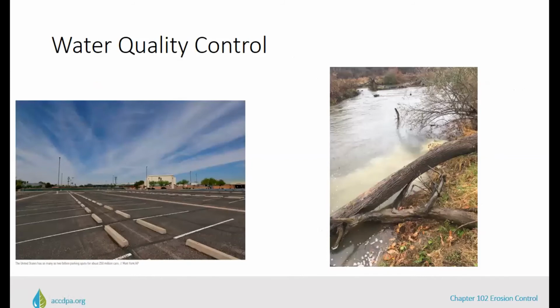Developed surfaces contribute pollutants during runoff and stormwater. For water quality, the regulations compare pollutant loads for different cover types pre to post development for total suspended solids, total phosphorus, and total nitrogen. BMPs need to be designed to manage the change and increased pollutant load for these 3 measurements after construction for the 2-year storm volume.